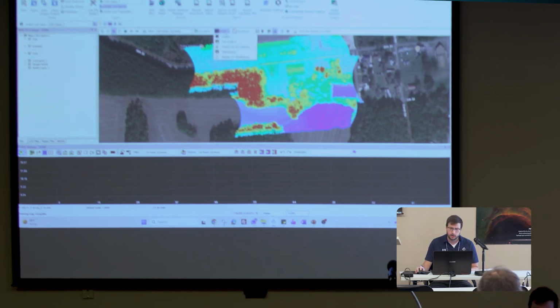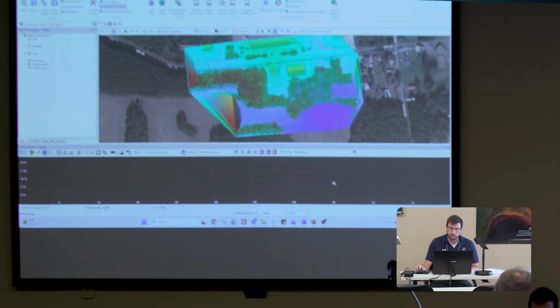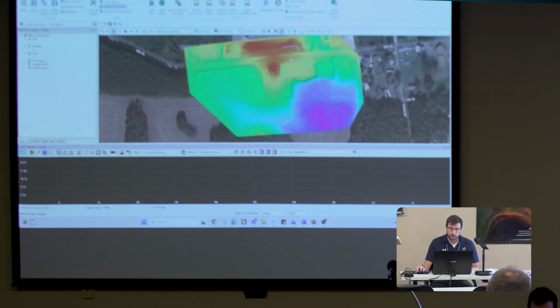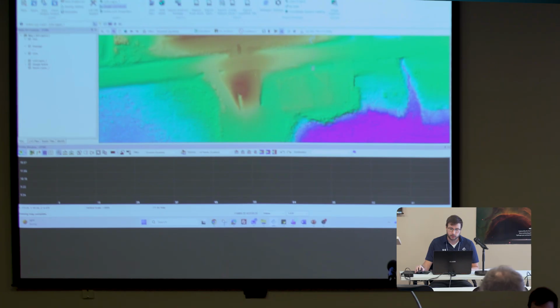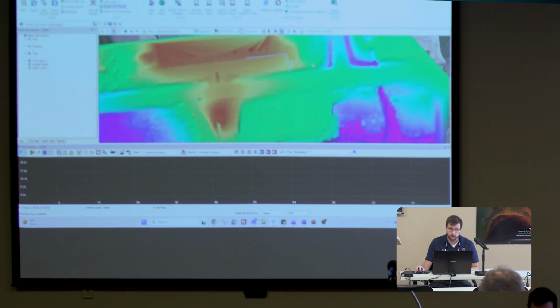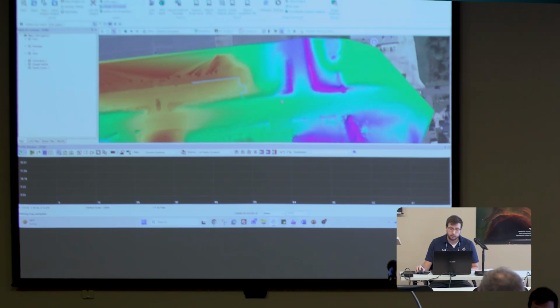So I'll click on the option to the right of the legend display for changing from point display to TIN surface, and some different options here. Click TIN surface. And then I'm going to switch the filter to ground. So we'll just look and see how the classification has been done, and verify, okay, does this look okay before we do the export?